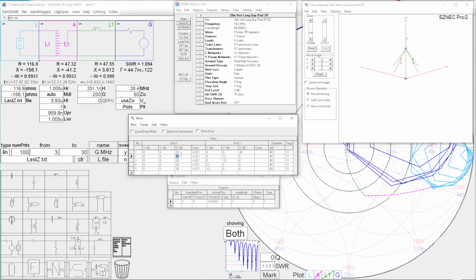So you can see it goes from 20 feet to 36 feet. That's 16 feet. That's the vertical radiator. And these go out from the center axis. They go out 12 feet, and they go down from 20 to 6 feet, which is about 14 feet. So away from the center 12 feet, down from the feed point by 14 feet. And so they droop down. Not quite 45 degrees, but close enough for government work.